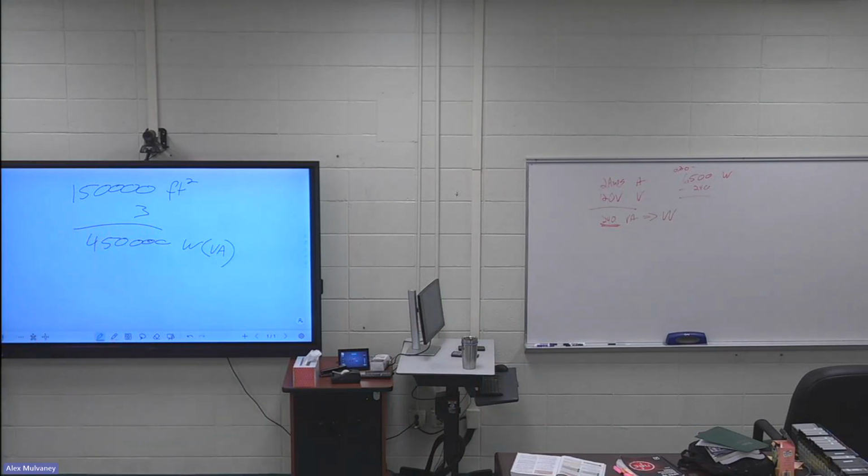Right? So that would be my first step in saying I need this much power at this building. Whenever they say general lighting load, they don't mean what's going to turn on the specific lights. Lighting load means everything. General lighting load is, to light up this building, how much is it going to take?